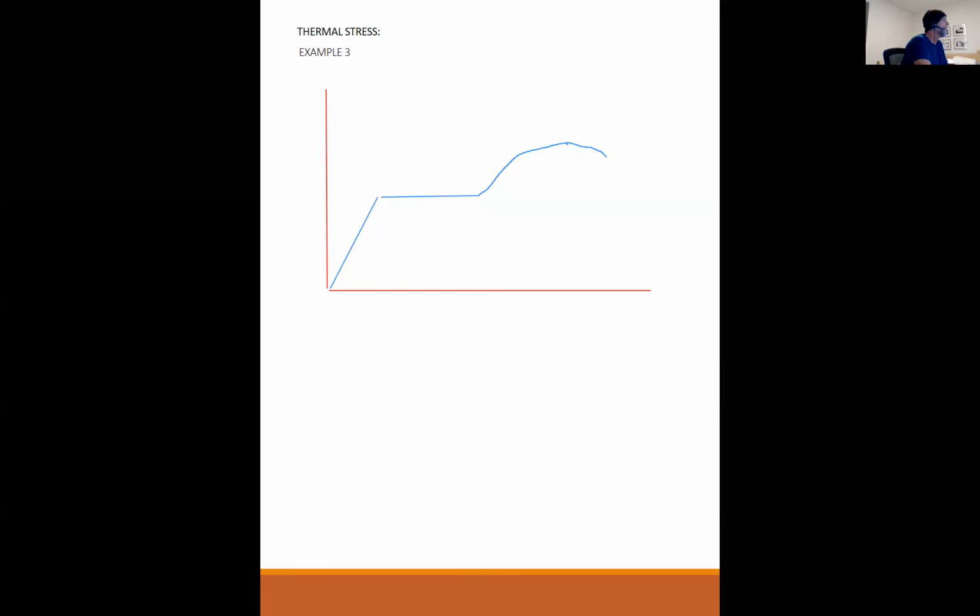But that sample is only representative of a sample that is wide enough and squat enough that it will not buckle. Buckling is a function of the slenderness ratio. So the narrower it is, the more tall and slender it is, the more that it's apt to buckle.